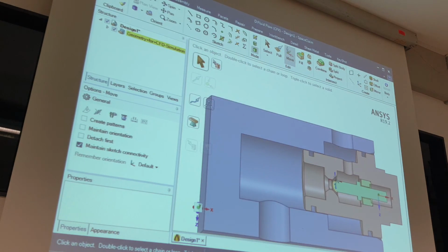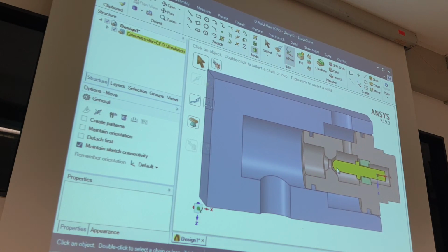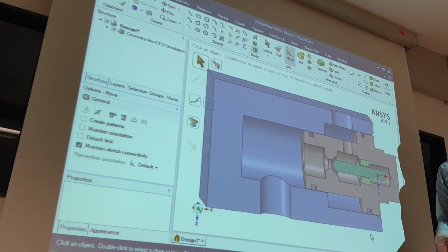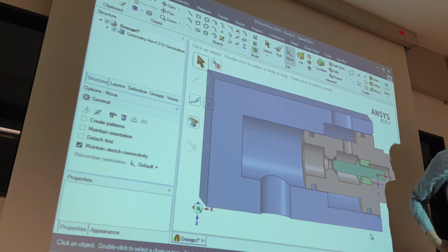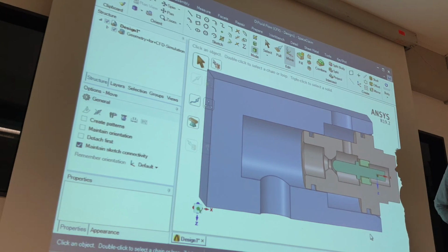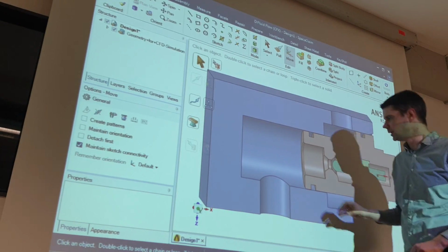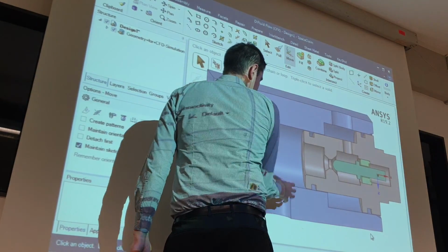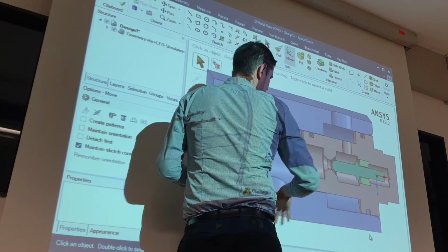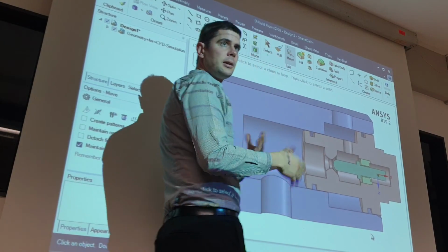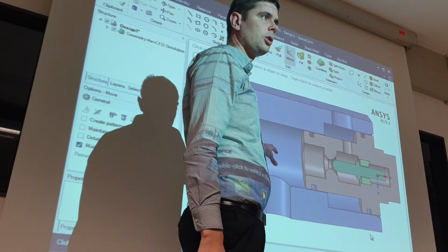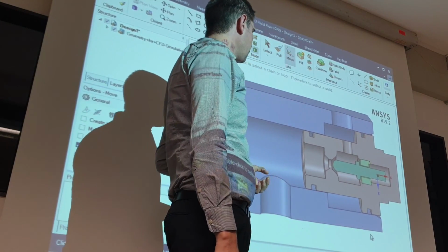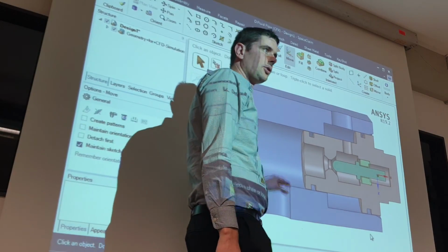And the first important thing for flow simulation: for mechanical simulation, I need my geometry. For flow simulation, I need the geometry of the flow. Yes, this is the first main thing. So I need my flow geometry. I need this negative geometry, like the negative of my geometry. So this is the main target. First, we need to create flow geometry.